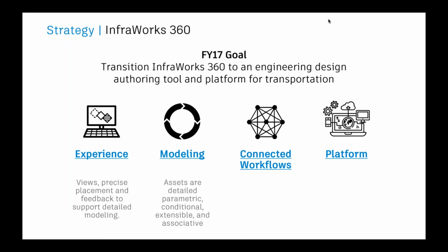And if you've used InfraWorks for any length of time, and you can think back to maybe 2 or 3 years ago, a lot of the assets that were in InfraWorks at that time didn't contain as much detail as they do today. So if you think about component roads, for example, compared to roads that you could model in InfraWorks a few years ago, component roads can contain a whole lot more information, a whole lot more detail, like design standards. They can respond to super elevation data. They can give you information about quantities.